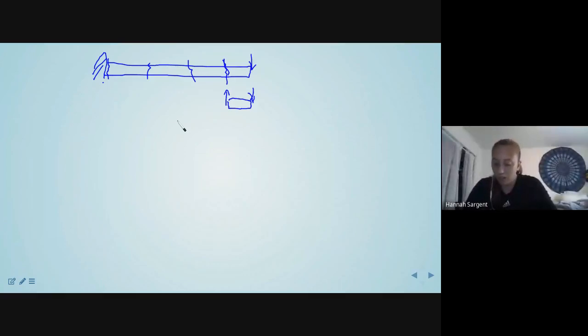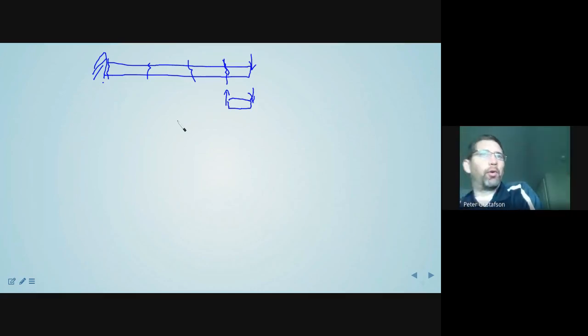Okay, so on the slide it said it was negative P, so would it be positive P if we're doing resultant, or do we just assume it's still in the same direction? Yeah, you have to be a little careful how you do those. The actual resultant you draw in the positive direction, although the shear stress that you draw, because it's on a negative face, you draw in the negative direction. And so if you're really attentive to your positives and negatives, then as I had noted it in my calculation, is how it's going to end up.